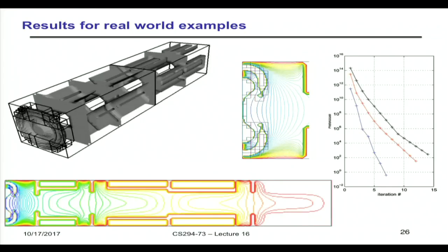And so I believe the convergence deteriorates a little bit as you add AMR levels. If you've got just a coarse level, we have that ideal convergence that I showed you before. But as you start to add these extra boxes and the interpolation algorithms between the coarse and fine grids and the complex geometry kicking in and out, you get a little bit of deterioration in the rate.